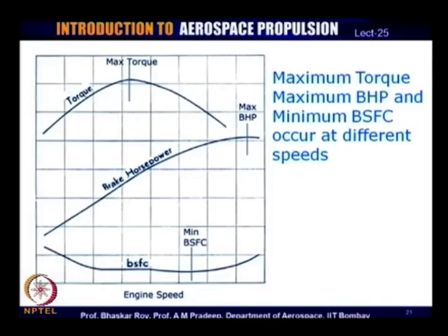And with the 2 controls together, we will have to find a balance of using the engine for maximum torque or maximum BHP or minimum BSFC, so that the total fuel efficiency of the engine is quite good and competitive and has an economic repercussion in the operation of the power plant. So, these are the issues that typically an engine operator, an engineer would have to deal with in the operation of the engine for flying an aircraft.